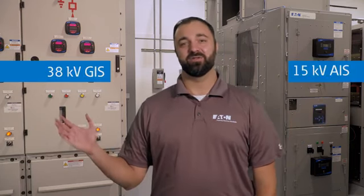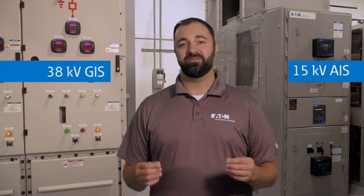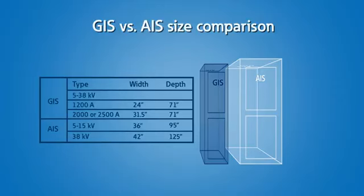operated, and maintained. Looking to my left, you will see a lineup of air-insulated switchgear, and to my right, gas-insulated switchgear. As previously noted, one major difference between AIS and GIS is footprint. For the 5 to 38,000 volt GIS structure shown, the 1200 amp GIS structure is roughly 24 inches wide, and the 2000 or 2500 amp structure is roughly 31.5 inches wide. The 5 to 15 kV AIS switchgear here has a common width of 36 inches for all bus ratings. AIS switchgear at 38 kV is typically a single high construction and is 42 inches wide.